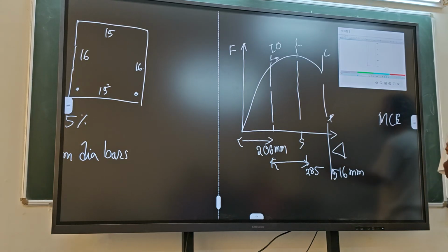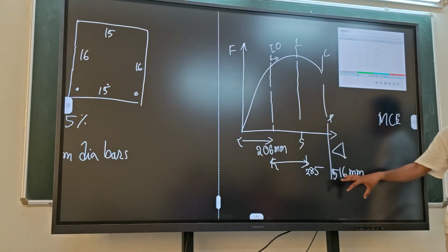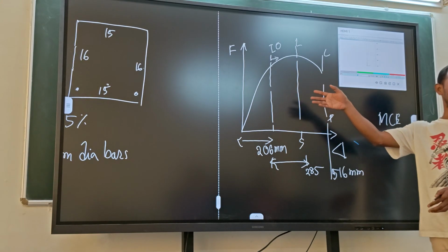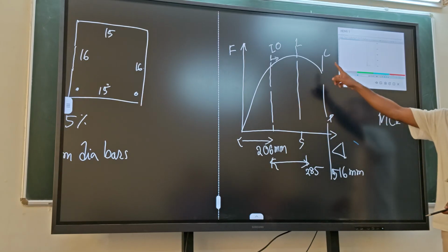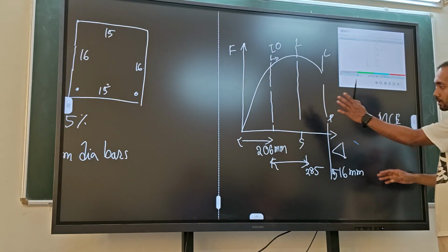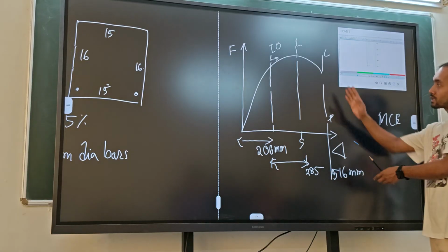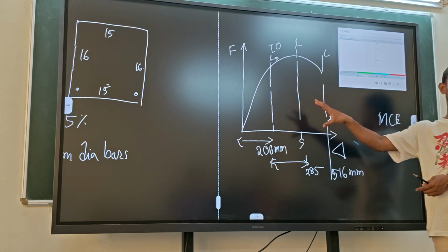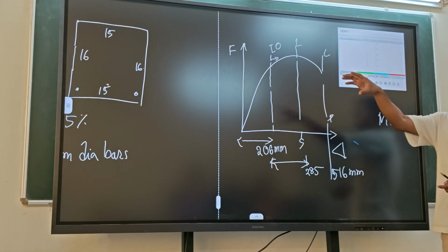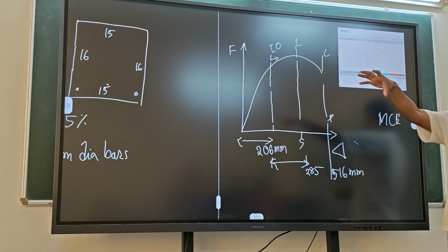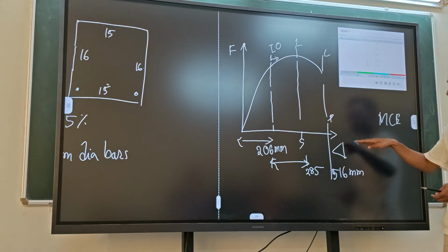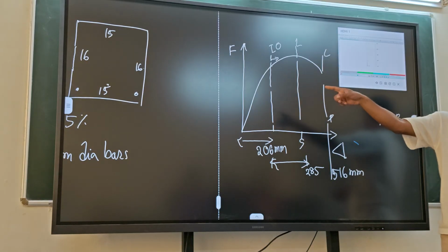Okay, that is the objective, but you do not design the building explicitly considering this displacement. Now this displacement can be different for different structures. For this structure, based on this analysis, I can say that this displacement is the CP level. Okay, this is the capacity estimate actually. Whatever columns we have taken, whatever reinforcement we have provided, whatever load is acting, based on all those things, this displacement is coming to be the CP of this structure.